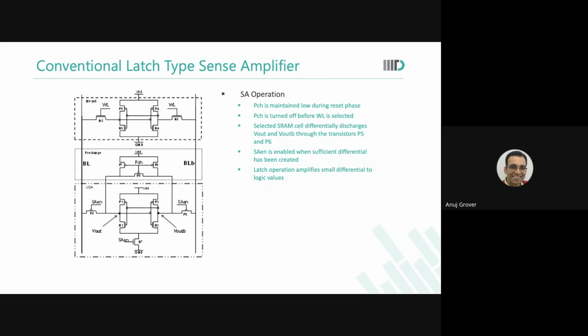The bit lines are pre-charged to VDD, and we are saying that the bit lines will discharge only a little. We're not taking them to VDD by 2. So using a PMOS is good enough. Or using a PMOS is anyways desirable because an NMOS would not even react at that level. For an NMOS, there is expected to be a VT drop. So the NMOS will not change anything inside the sense amplifier if I use an NMOS as a connecting or coupling device there. So to couple the sense amplifier to the bit lines, I need a PMOS.